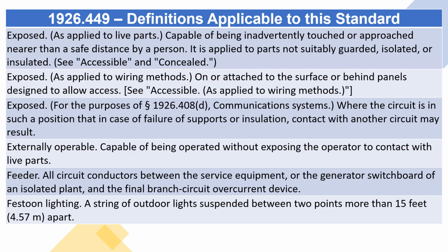Exposed. As applied to live parts. Capable of being inadvertently touched or approached nearer than a safe distance by a person. It is applied to parts not suitably guarded, isolated, or insulated. See accessible and concealed. Exposed. As applied to wiring methods. On or attached to the surface or behind panels designed to allow access. See accessible.